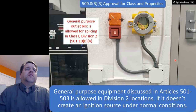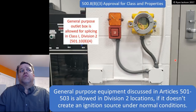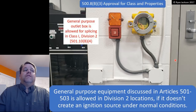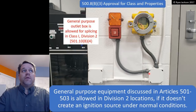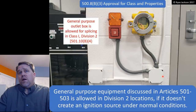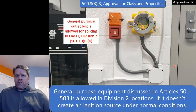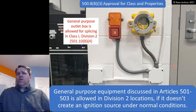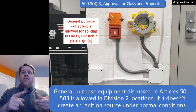Item B3 is something that really throws a lot of people. General purpose equipment, discussed in Articles 501 through 503, is allowed in Division 2 locations if the equipment does not create an ignition source under normal conditions. So here we have this general purpose 4 square box or 1900 box, depending on where you are. This is okay in a Class 1 Division 2 location. We're not expecting explosions in Class 1 Division 2 locations. It requires two bad things, right? Some sort of an incident and a source of ignition.